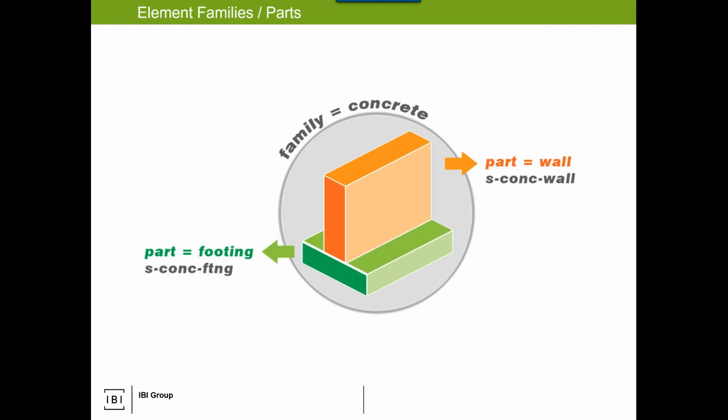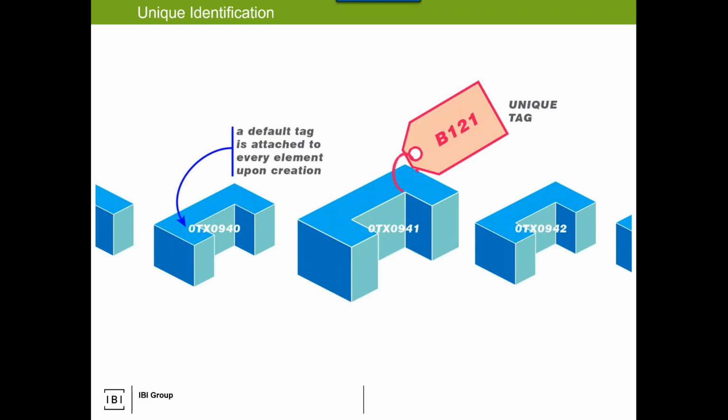Start to get into some interesting parts though. Oftentimes we're asked for quantities, and whenever we're dealing with quantities, the biggest ticket items are usually your steel, concrete, and pipes. Now, when you think of traditional buildings, steel and concrete are still the biggest items. Architectural finishes come into play often as well, but in infrastructure and industrial, concrete and steel come up all the time. And what we look to do is, again, remember that 4-step. What are you modeling? How do you model it in your component? And what's that unique tag?